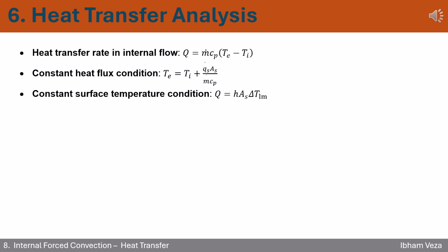6. Heat transfer analysis. Let's make heat transfer analysis simple and useful. The total heat transfer rate in internal flow is straightforward. It's just mass flow rate times specific heat times the temperature change between inlet and outlet. This tells you how much energy the fluid is carrying.